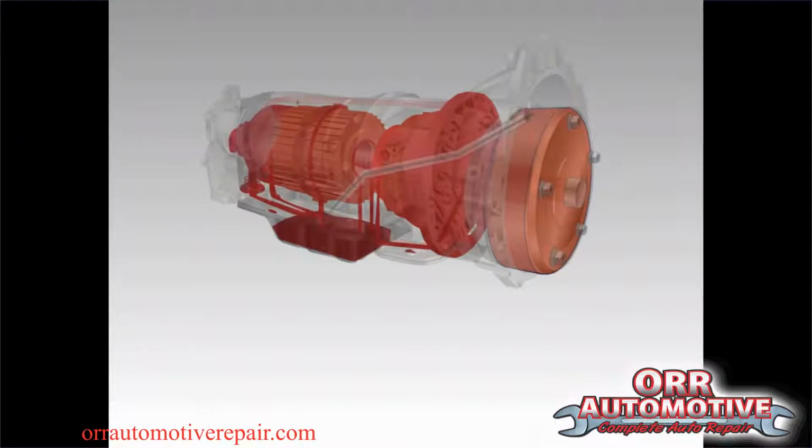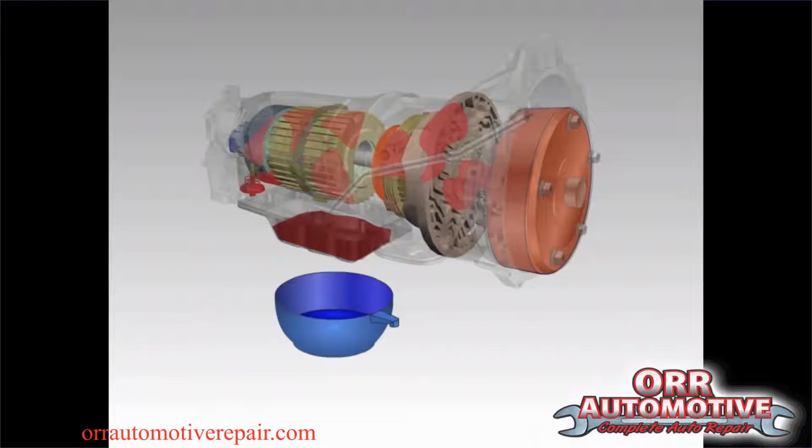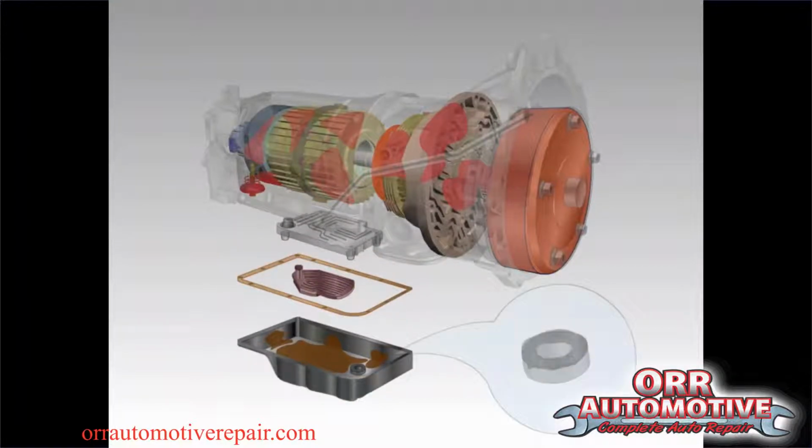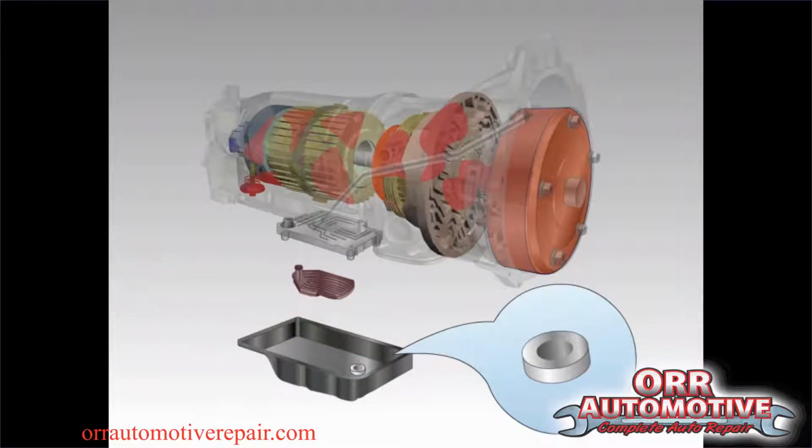The drain and fill service often includes replacing the transmission pan gasket and internal fluid filter. First, the drain plug is removed to allow the fluid to leave the transmission. The pan is then removed so access can be gained to the transmission filter. The filter is removed and debris is cleaned from the transmission pan. After installing a new filter, the pan is reinstalled with a new gasket.